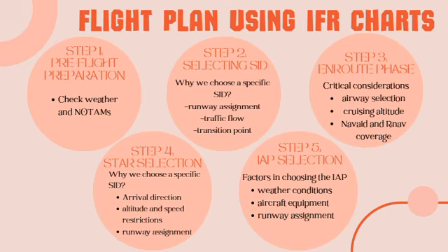Because of the arrival direction. The STAR must align with the direction of approach to the destination airport. Also, the altitude and speed restrictions. These are critical for sequencing with other aircraft. We must verify the aircraft can meet these restrictions.